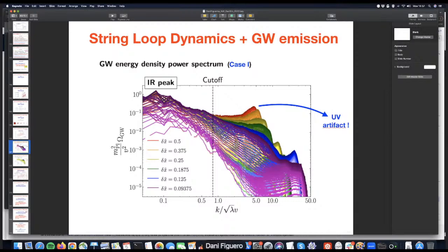And in this resolution with this dx, if I have 0.09, it really means that I have of the order of 25 points inside the diameter, which means you have of the order of 500-ish points in the cross section. Okay, that is a super high resolution. That is a very good resolution.